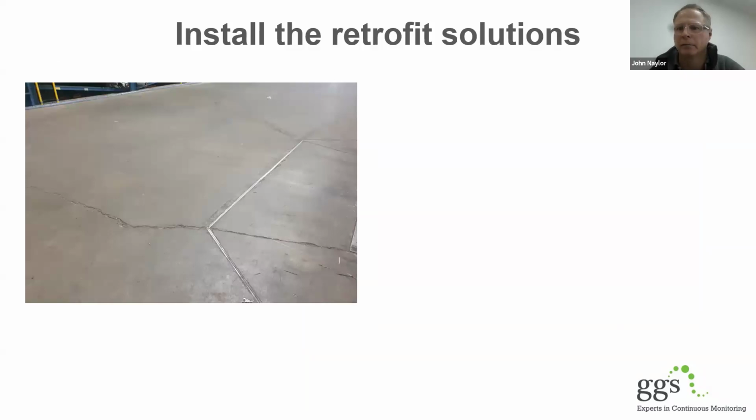What about cracks? Let's talk about concrete. I'm no expert in concrete, but whenever I've done investigations looking for ingress, it's usually gaps or cracks in concrete where we find it. That's a major crack you can see in that photograph. It does happen. Interestingly, these cracks don't happen instantaneously. This could be 5, 10, 20 years down the line.